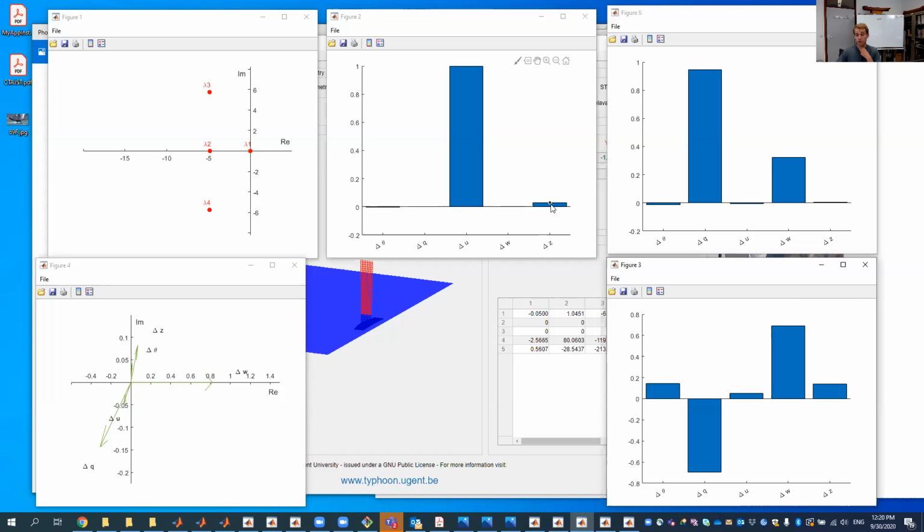What we see here is that we have a coupling between the elevation and forward speed, a neutral coupling, which is lambda 1, which is something we expect. Then here we have a wobbling motion, a coupling motion between the heave motion and also your pitch velocity. So it's some kind of wobbling motion, which is oscillatory in nature. Another exponentially decreasing eigenvalue we have here is a coupling between the heave motion, the pitch velocity, and so on.